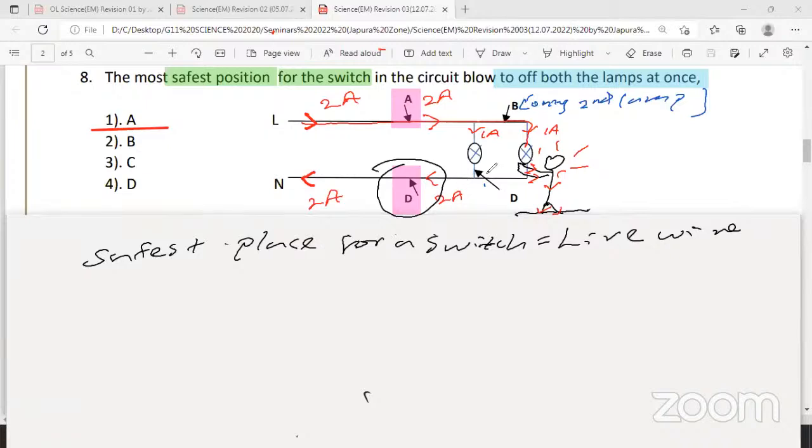Therefore, during house wiring, electricians, you have to be careful. Make sure they connect the switches to the live wire. So there are two-way switches and single or one-way switches also. Because after covering this with the casing and the plug base or the socket, you can't see the wires inside the wall, inside this conduit tube. So you don't know whether they have connected the switch to the live wire or the neutral wire. You can operate the lamp, you can switch on and off even from the neutral side, but if you are going to do a small repair by yourself or replace the holder, because you don't call the electrician to replace the lamp, right? So you take a new lamp or new bulb and replace it, right? So then there's a risk. So you understood the point.